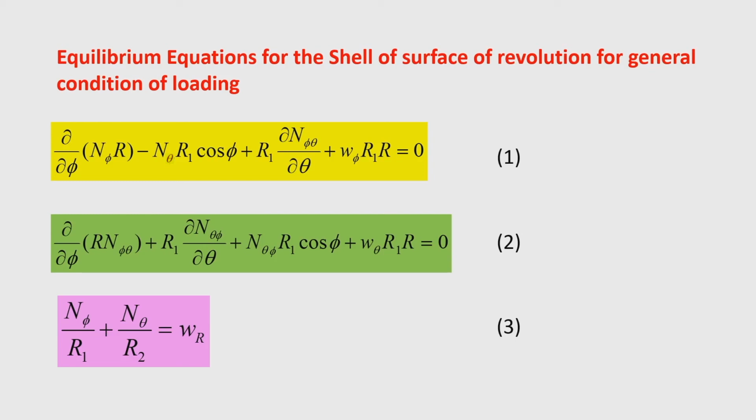Now, mainly the shell structures which are used for construction of a roof, say a dome in an assembly hall or a religious place or any large hall, is generally a thin structure and the loading there is only self load and a very nominal quantity of live load, and occasionally wind load occurs, and wind load of course becomes an asymmetrical distribution.